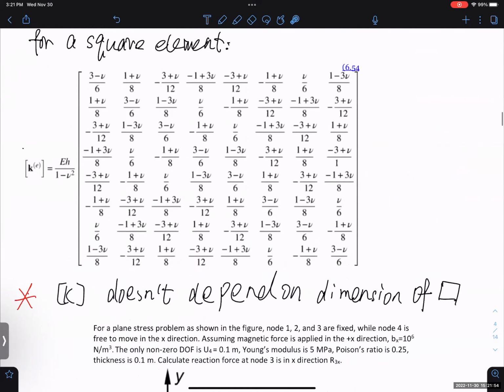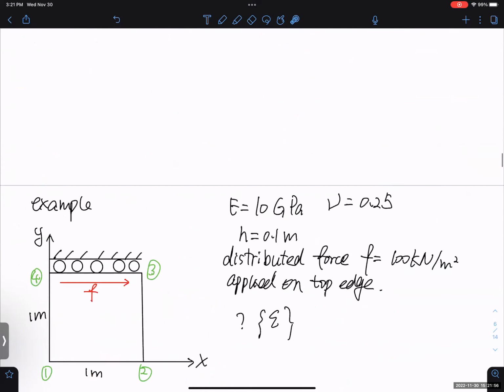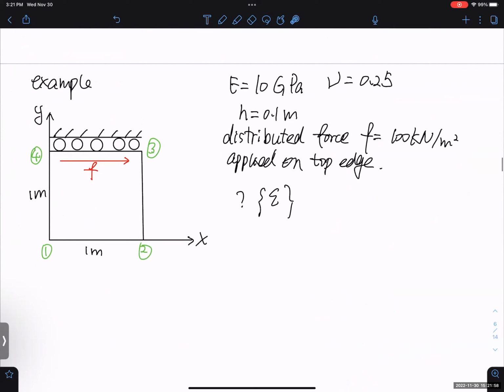And also, let's continue on this one. For this one, it is distributed force, but it gives you the exact result. So don't just conclude that if you consider force, a distributed force means approximation. No, it really depends on different element types, different structures, different boundary conditions. Right? We were dealing with a beam problem, which is a different thing.